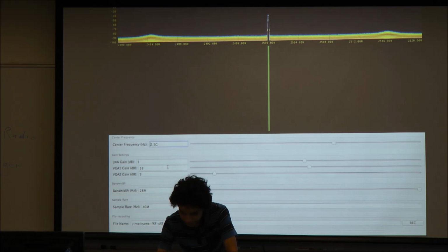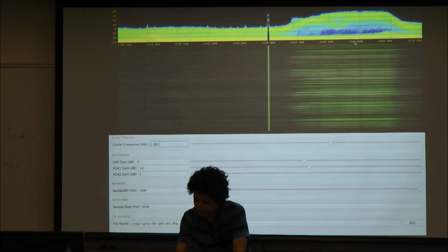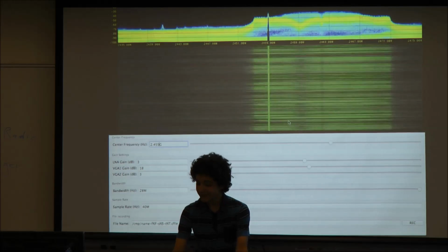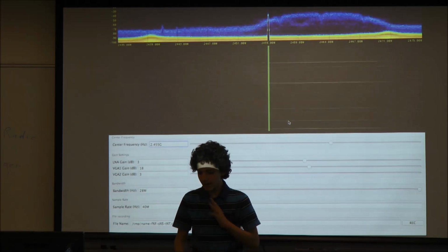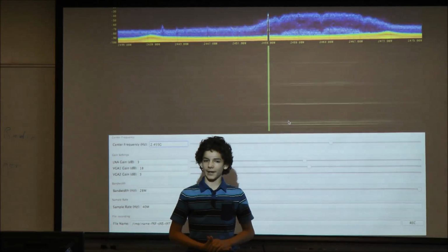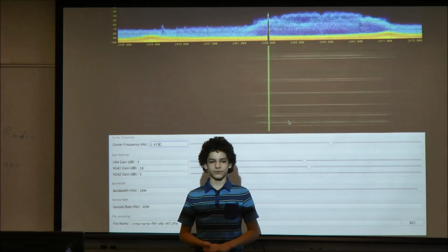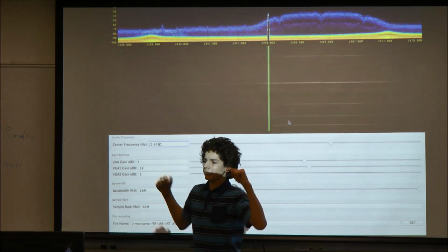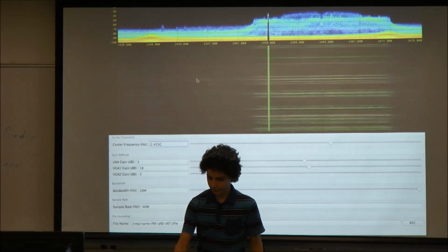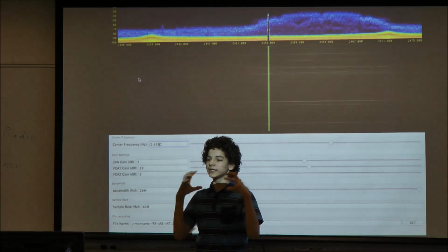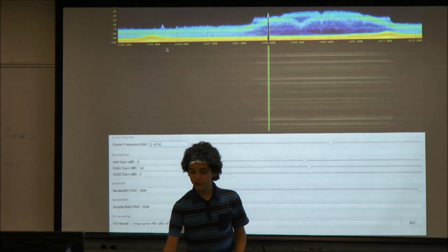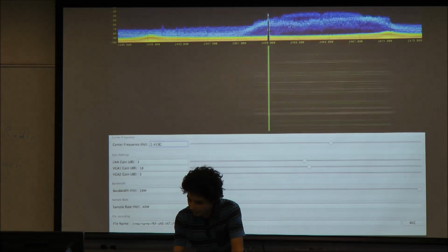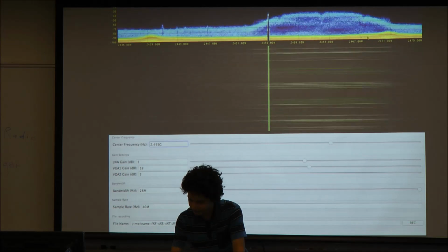And also you can see with the 2.45, if we look here, here's the DC offset. This is running really fast, which is cool, so you can see all this stuff. And are any of you familiar with a real-time spectrum analyzer? Okay, a few of you. It's a really cool thing. It's sort of like this, essentially, where you compute the FFTs, which gets you this frequency versus amplitude really, really, really quickly. And then you do color gradients for what happens a lot. So if we look here, we can see there's a signal here, but it's pretty brief. And then here we can see noise.